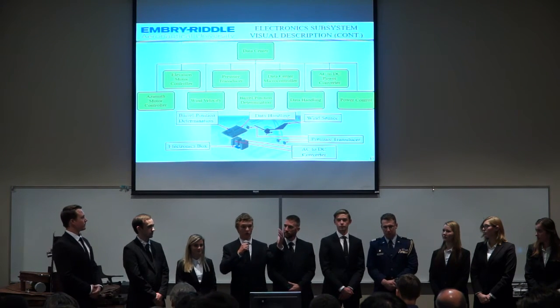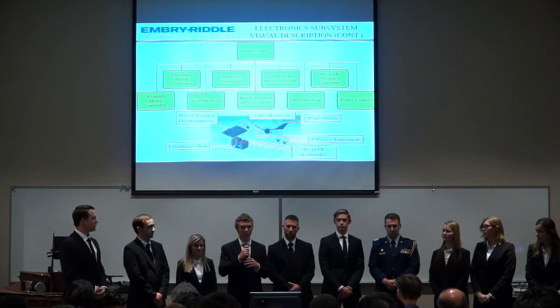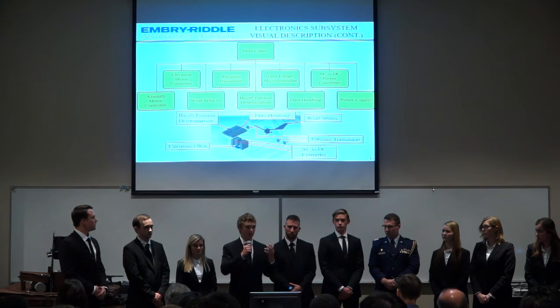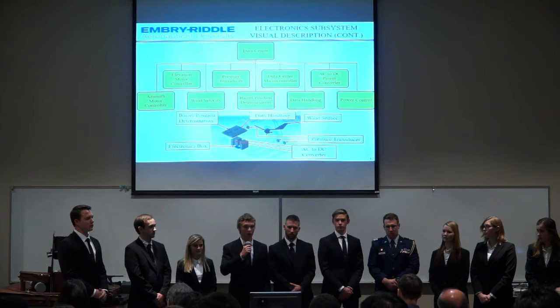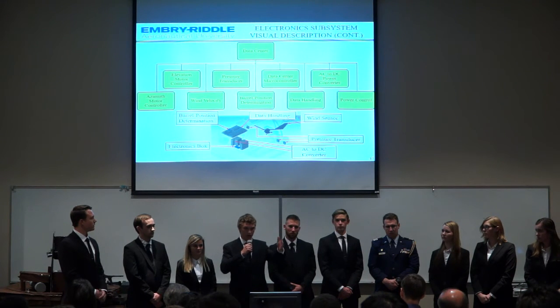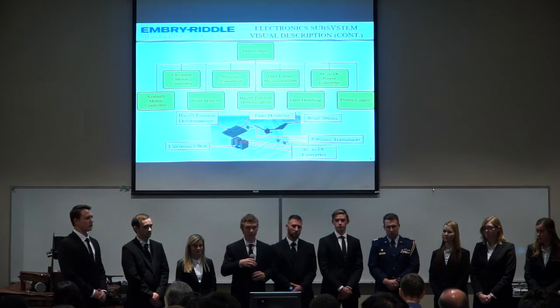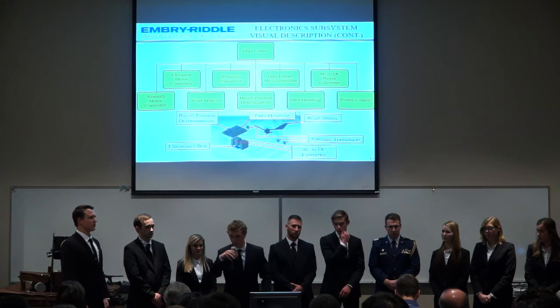So in terms of the launch guidance orientation, which is our barrel orientation, on the top there is that barrel position determination, which is a magnetometer and an accelerometer. That will be able to give us a heading and then our elevation as well, and that's used in a closed loop control system to figure out where we are. Okay, just want to make sure you had some redundancy. Good, thank you.